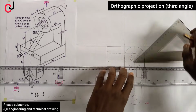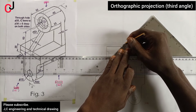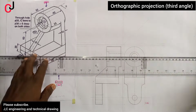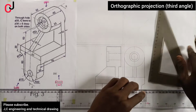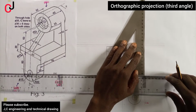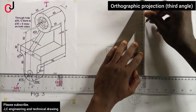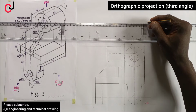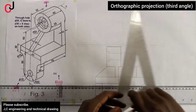So use our 45-degree set square, or produce an angle of 45 degree, and then from our side view we'll project upward once it hits our 45 degree. We'll project to the left. We also project from our front view.